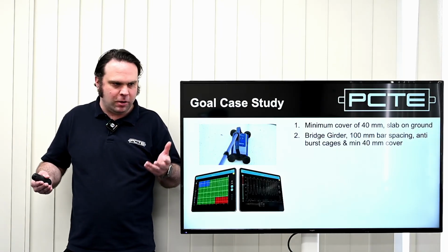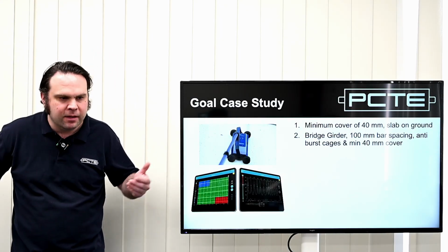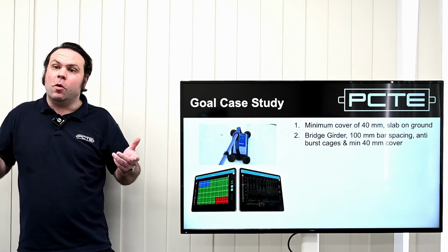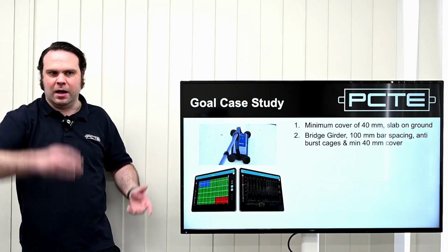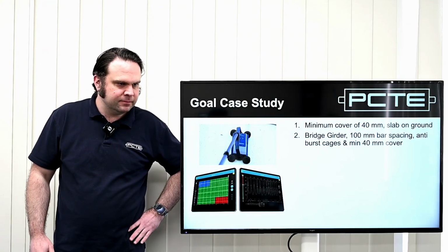40mm cover requirements, but maybe some additional reinforcing, some very tight bar spacing, 10 centimetres apart. How does that change things? What do we need to be aware of now? Would you have some interference from the other bars around you? Yep, exactly. So if you're using the profimeter, you might use some of the neighbouring bar correction functions or other resources like that to assist you to measure that precisely.